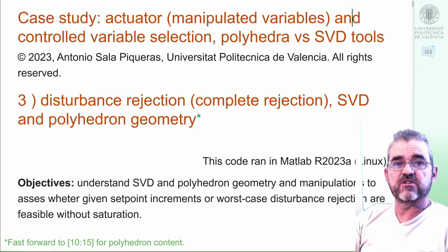So, this feed-forward transfer function will be the one that would compute the needed input, but if G is not square, then we are lucky, we have infinite solutions, so we will produce the one with minimum norm of U using a pseudo-inverse, and of course a pseudo-inverse over the scaled units, so that all inputs have the same technical meaning.